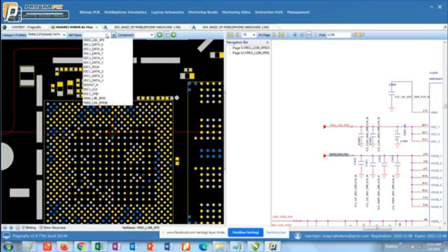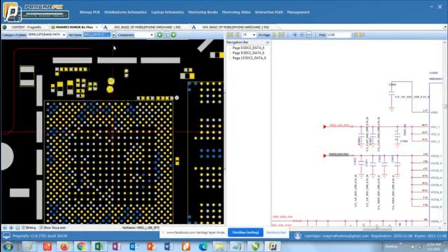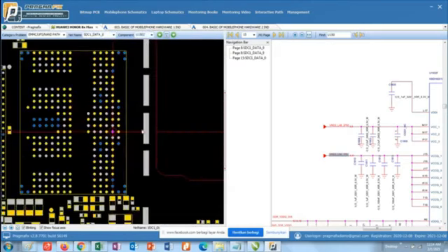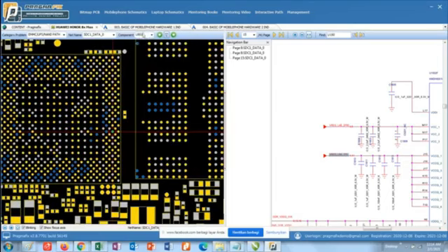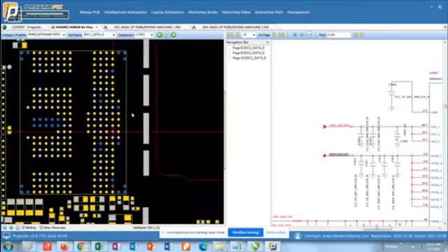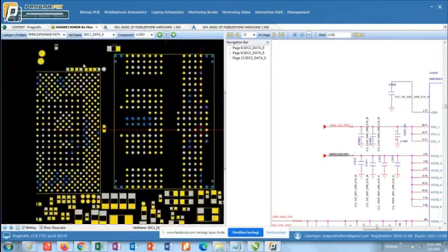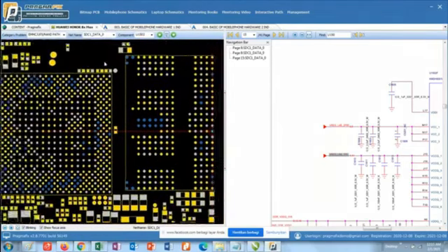After this you pull it out, it is too hot. After we remove and replace again, using the other eMMC, this does not want to work. You guys try the eMMC 3 or 4 times, but apparently forgot to check continuity in this lane.